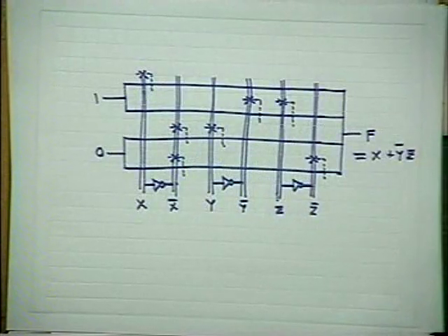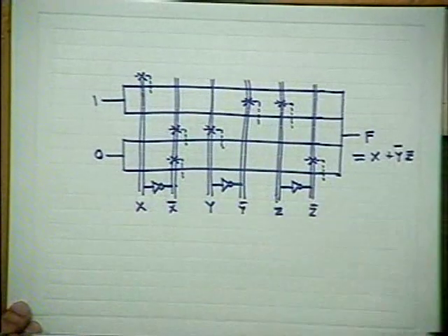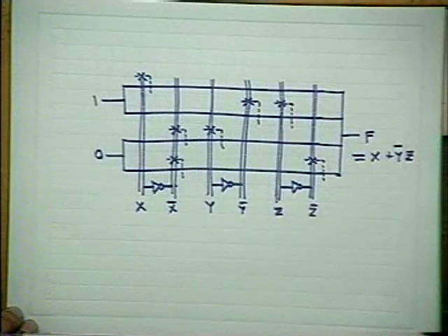Already available. Then according to a demand, you tell the company that you need this. You will sit down with the computer and design two things: a mask for these contact holes and a mask for input output, because bonding etc. has to be done, so that kind of information is necessary. Otherwise, metal lines are a very simple thing. The standard masks are available where metal lines are just rows and columns. Only holes are needed. That's all.